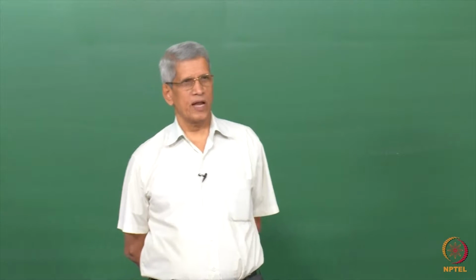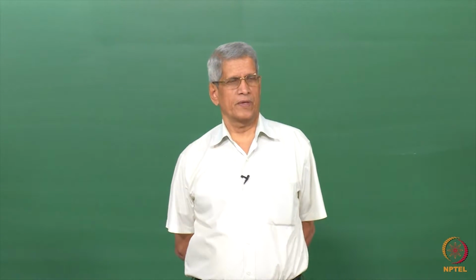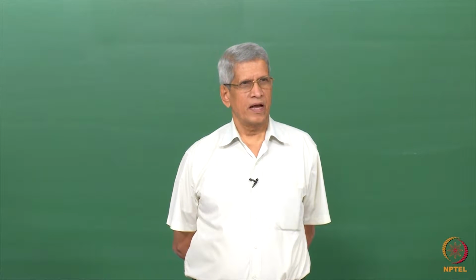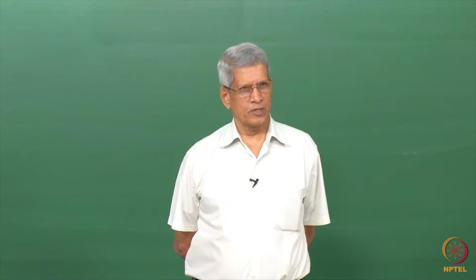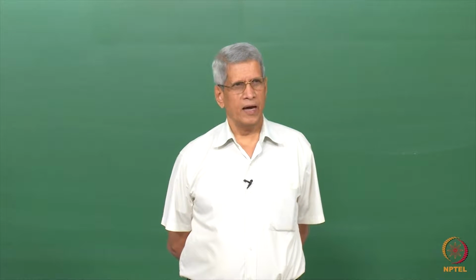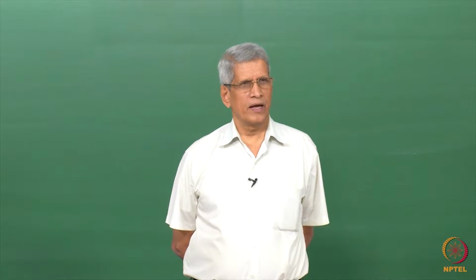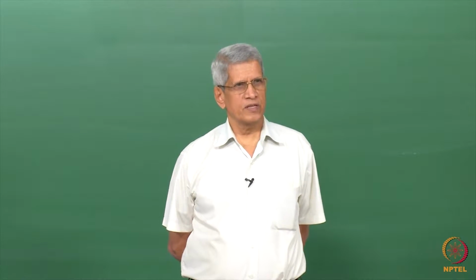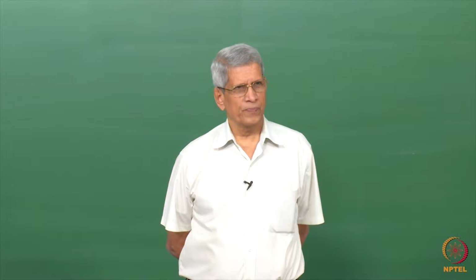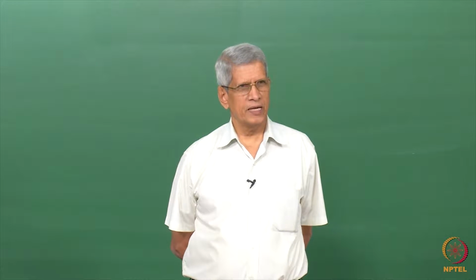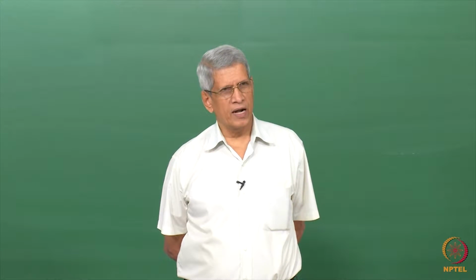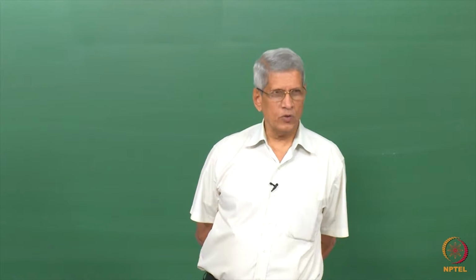In the last two classes, we have studied the stress and strain field around screw, edge and mixed dislocations, and also, because of the stress and strain field around the dislocation, the increase in energy which will occur in the material, which is called the self energy of the dislocation.